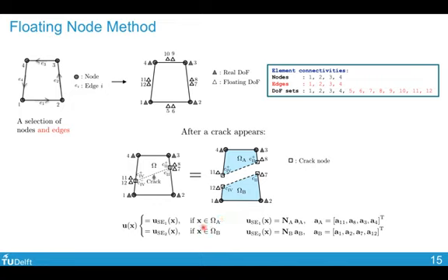So if your x lies within omega A, you have the displacement field of sub-element 1 to represent this displacement, and then if your x belongs to omega B, similarly you have the sub-element 2 displacement field. Each of these sub-element displacement field can be obtained by a straightforward standard finite element interpolation using the standard finite element shape functions for the respective sub-elements.